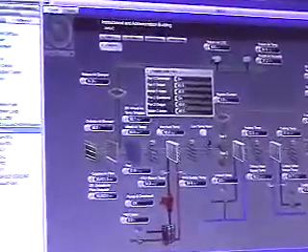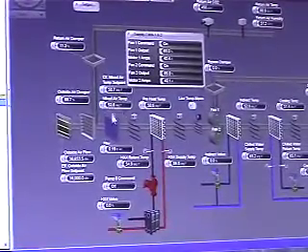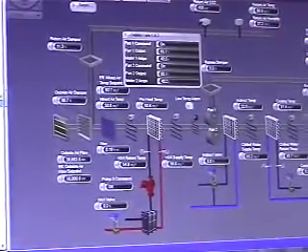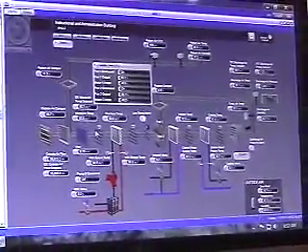Economizer is just going to open and close the dampers to modulate them until your outside air temperature gets above your mixed air temperature set point, and then it'll jump to the next state. In this mode, in state 2, we're controlling the mixed air dampers to the mixed air temperature sensor right here. So we're not relying on this discharge air temperature sensor, we're relying on the mixed air sensor right here. So that'll go up and down.